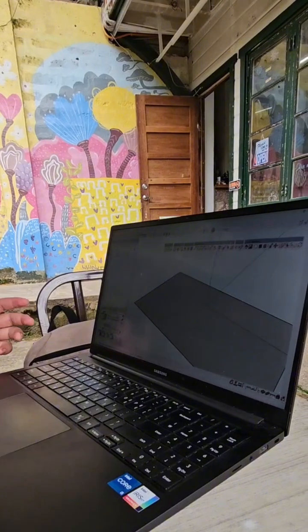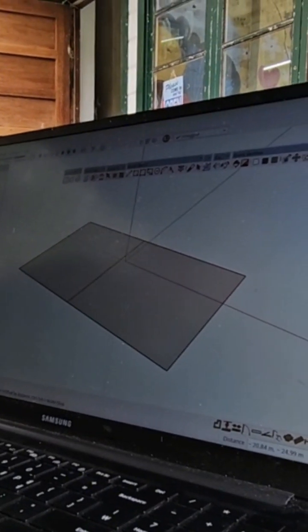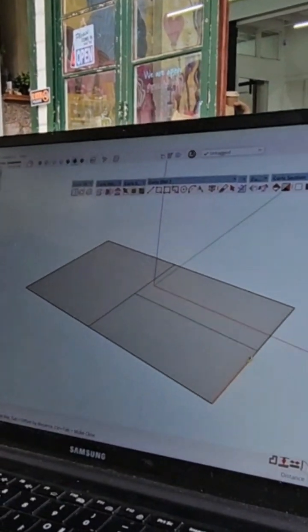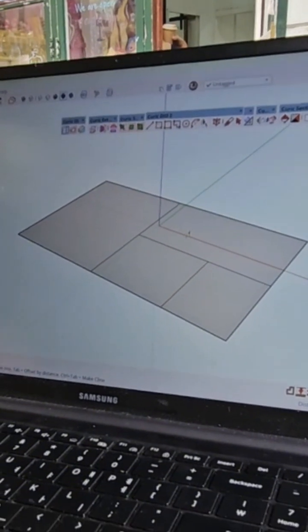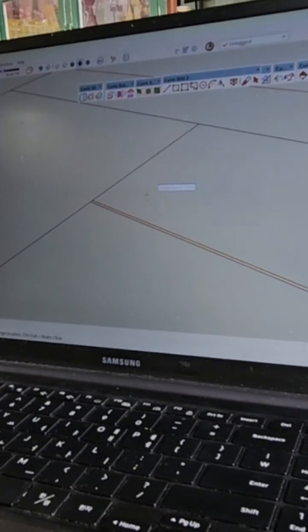The first extension that I bought ever in my life in Sketchup is called the Curic extension. The first thing I will show you is called Curic OI. Let's say this is a simple plane or rectangle. Using that first Curic OI called chalk line, I can use it like a tape measure tool, but actually to make some walls. And if I press the control button, it's going to make a double line.